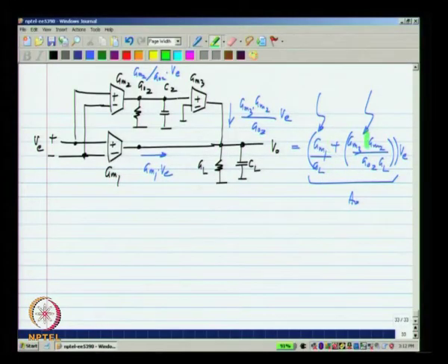Okay. The 2-stage Miller compensated op amp, after we implemented all the stages using transconductors, had this form. It was the product of 2 GM by GOs. Similarly, here we also have this one added, but GM3 by GO2 is likely to be a large number. So, most of the DC gain is provided by this path, whereas this provides a modest amount of DC gain. Whereas this performs the function of integration that is required inside the op amp, the GM1 and CL together, and the other path provides the DC gain. Okay. So, our idea has worked and we have got an op amp with a higher DC gain.